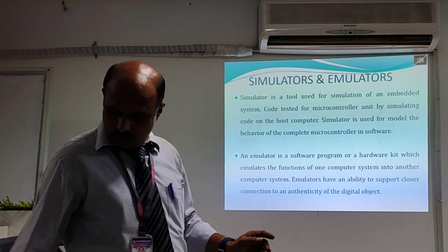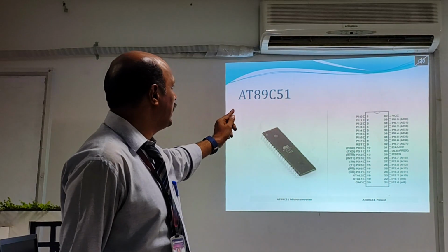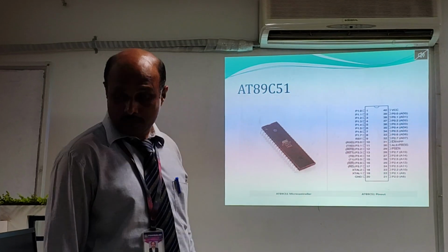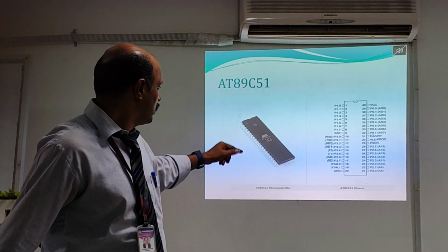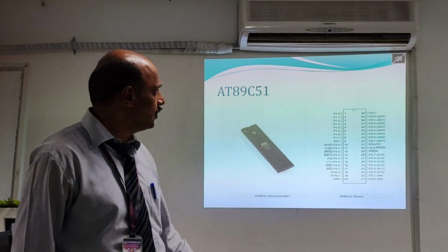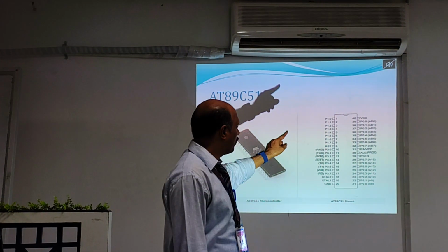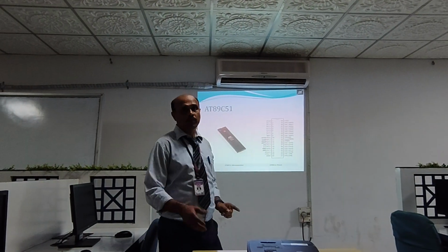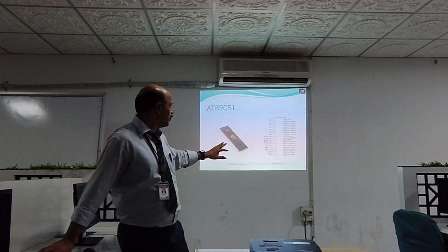Next, this shows that the 8051, AT89C51, is the microcontroller used in real-time embedded systems. It contains 40 pins. Out of that, there are four ports: P0, P1, P2 and P3, which can be used as both input and output. So there are a total of 40 pins.